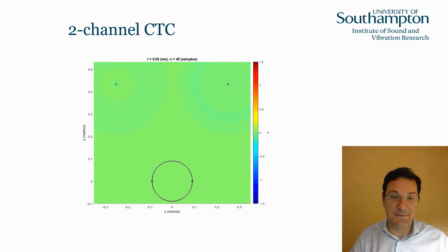So what you can see here is again a horizontal cross section of a sound field. You can see here the left loudspeaker, the right loudspeaker, and this is a human head, again with a shadowless head model, the left ear and the right ear. We're going to try and deliver a perfect pulse at one of the two ears, and let's see what the crosstalk cancellation system does.